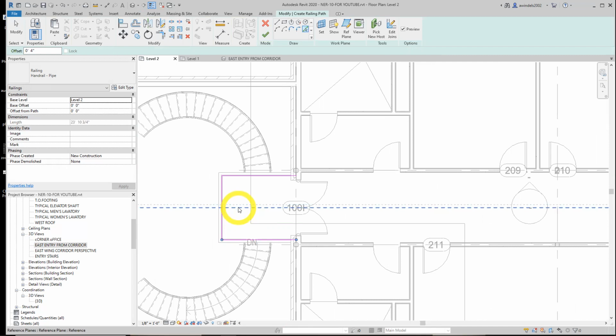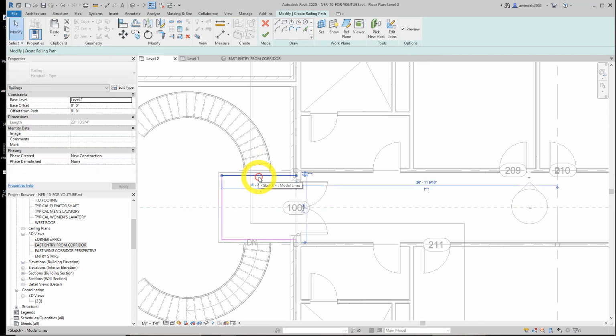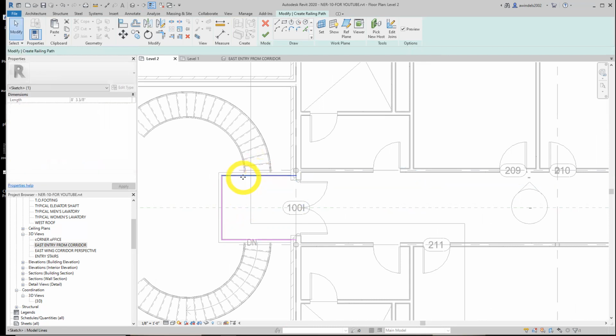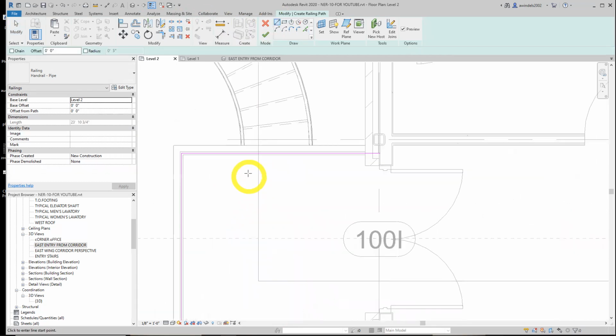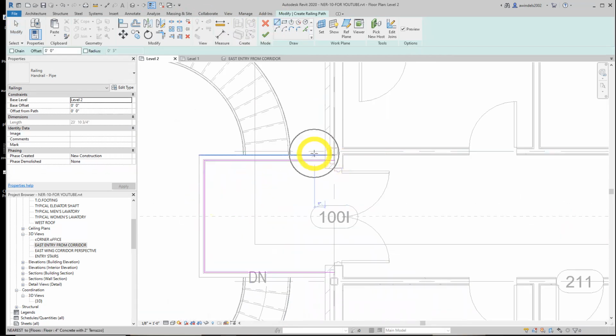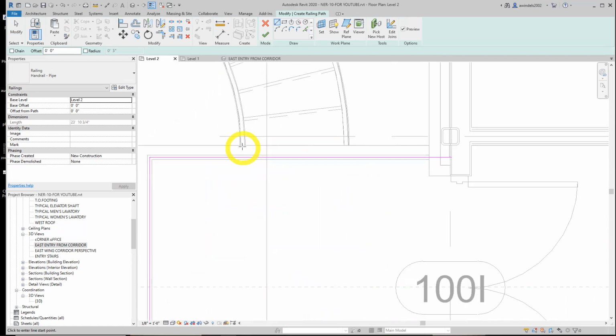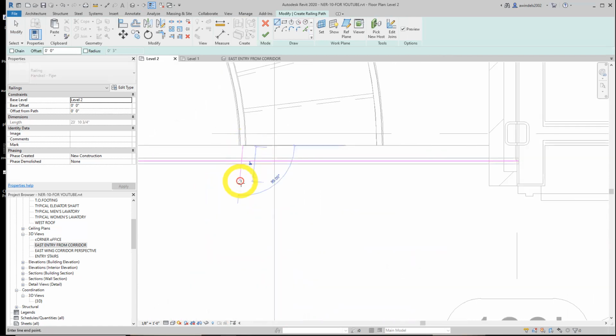Let's see what it has on figure 9.2. So we're going to create one railing like this. Let's hit escape so we're off of the pick line command. We're going to draft a line now. We're going to make one railing over here, then we're going to make them over here. We'll see what that means in a minute. Endpoint, draft it here, hit escape.